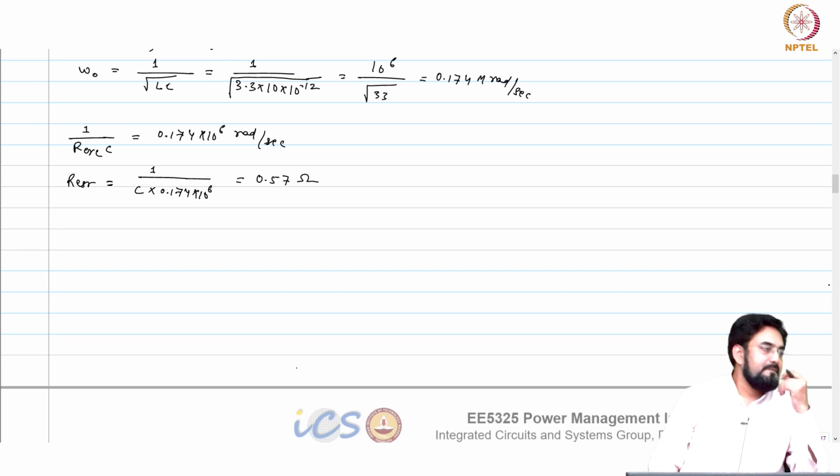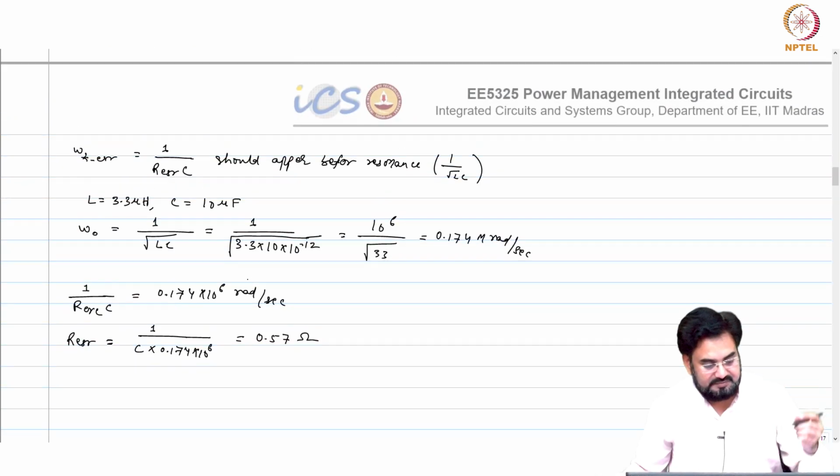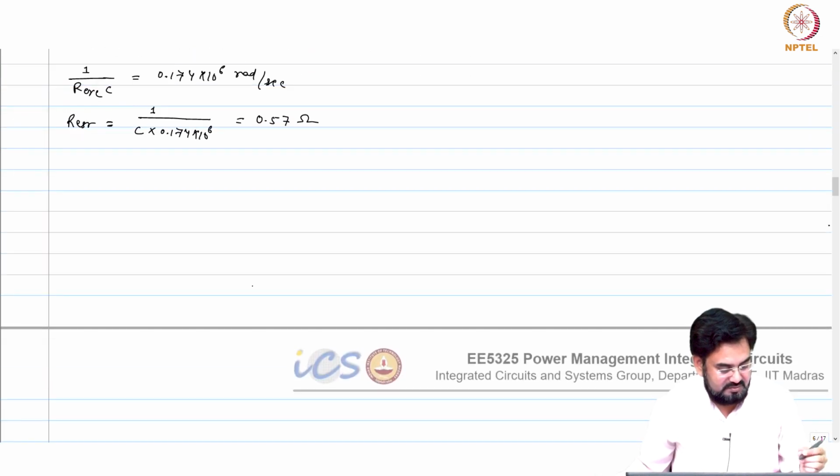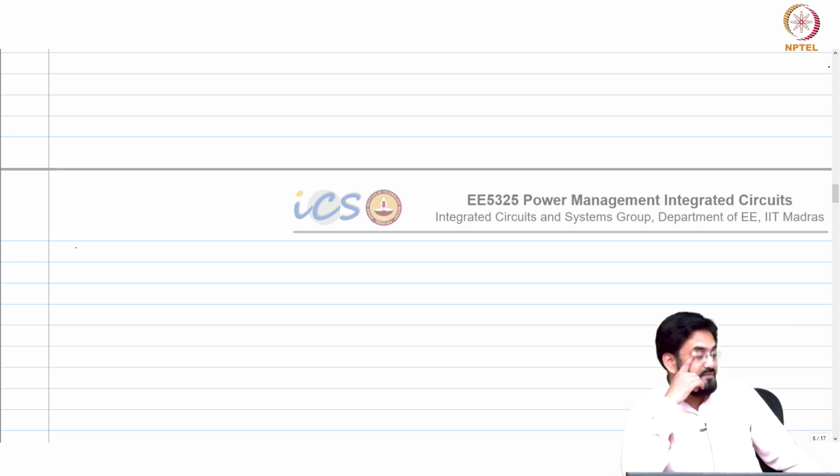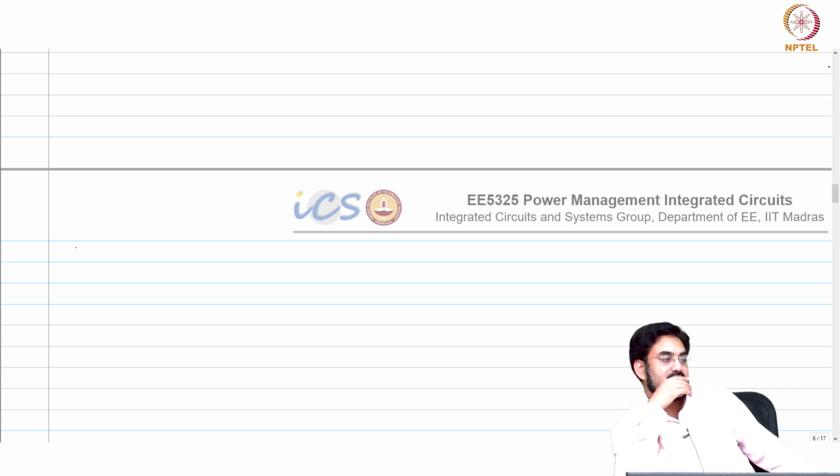So, how do we choose the gain? So, now 0 you have placed, you need to find the proportional gain. Okay. So, where will you place the first 0? Before the or at the resonance frequency, you can put that also, it is not a problem.